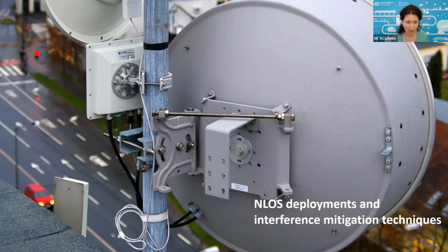What causes VSWR and how can someone avoid that effect? Okay, VSWR is obtained when the device's impedances do not match very well, when there is a mismatch between the impedance of the load of the antenna and of the circuit. So what is recommended is to properly install the antenna and the components and make sure that the VSWR is fine. So you should have a match between the impedance of the antenna and the impedance of the circuit.